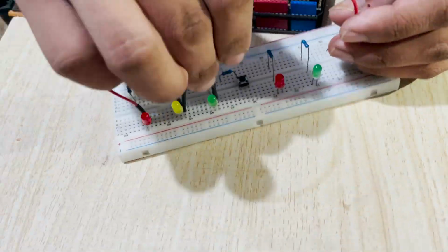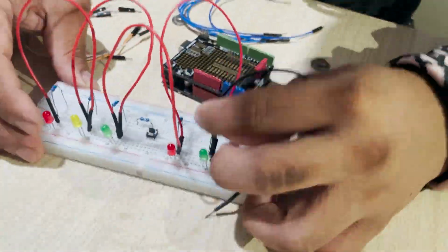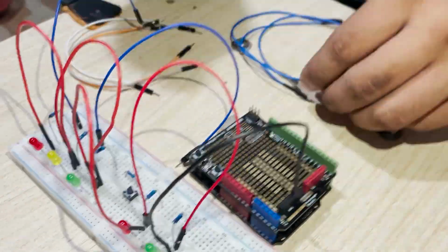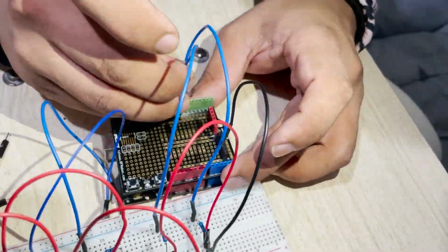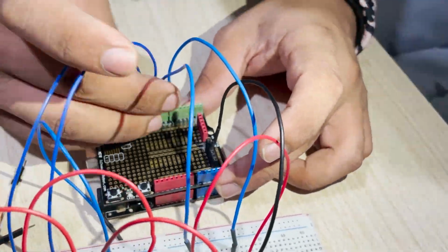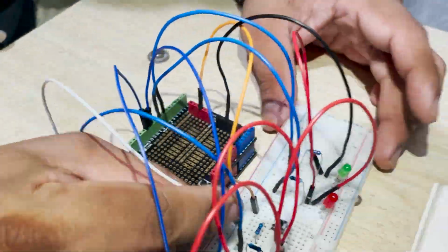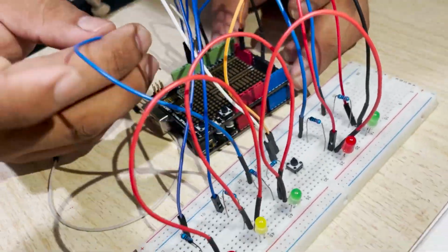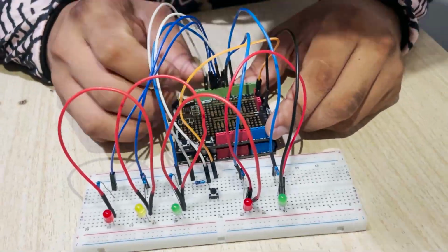In order to make it look more presentable, we would connect the negative pins along with the next negative pin, up until the final wire connects to the ground pin. Then next would be connecting all of the LEDs into the analog pins. Lastly, connect the push button wire to the 5V pin, and at the end of the resistor, the push button connects to the analog pin.